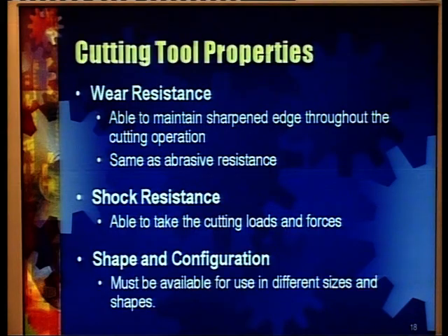The fourth very important property, in case of tools like those used in a lathe machine, and very important where the tools are fed intermittently, is shock resistance. The tool material should have sufficient toughness so as to be able to withstand the shock it comes across while the machining is being carried out, so that the tool edges may not break off.